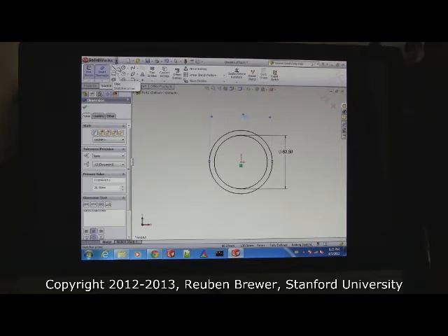Now we're going to draw a line. There are two types of lines in SolidWorks in terms of straight lines. And you see where my icon is here? You see how there's a little arrow? That little arrow lets you select between the two lines. We can either do a solid line or a center line. So in SolidWorks, if something looks solid, it means it's a real dimension. It's going to use that when it makes the extrusion. If it's dashed or dotted, it means it's just there for helping you make the sketch, but that won't appear in your final part. So what we're going to do right now is it's called the center line, but basically the dash line.